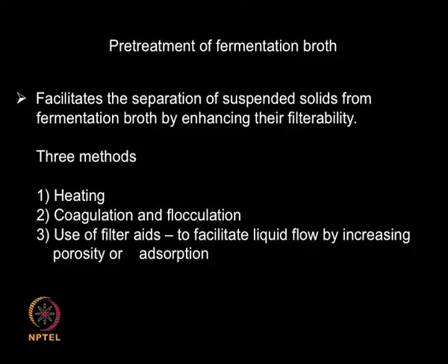So a few of the important techniques which are adopted for improving the filterability include heating. That means you heat the material which you are going to filter. You adopt something called coagulation and flocculation, or use something called filter aids. These filter aids improve the flow of the liquid through the filtration unit, either by improving the porosity of the bed or doing adsorption of some of the unwanted solids which hinder the filtration process. We will look at each one of these techniques slightly in more detail.